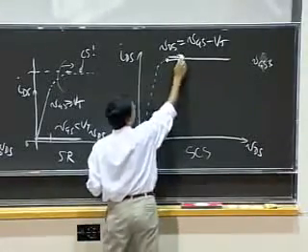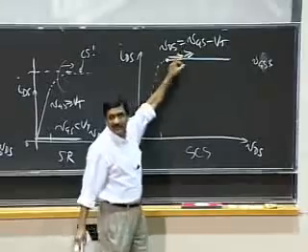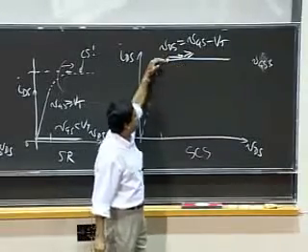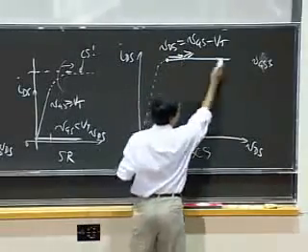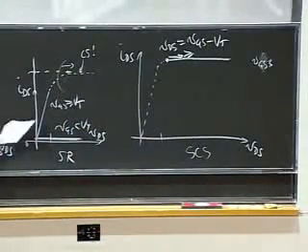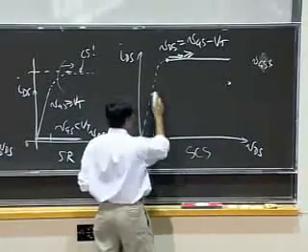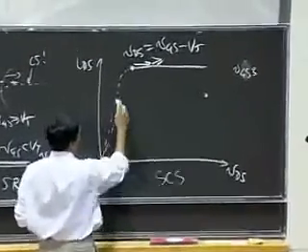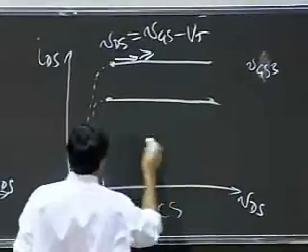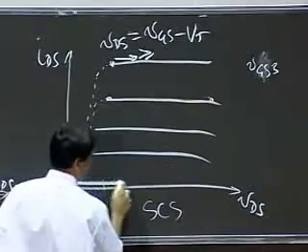And this way is when this equal sign becomes a greater than sign. As VDS becomes larger, I move into this part of the curve. Similarly, for various other values of VGS, it'll look like this, and so on.